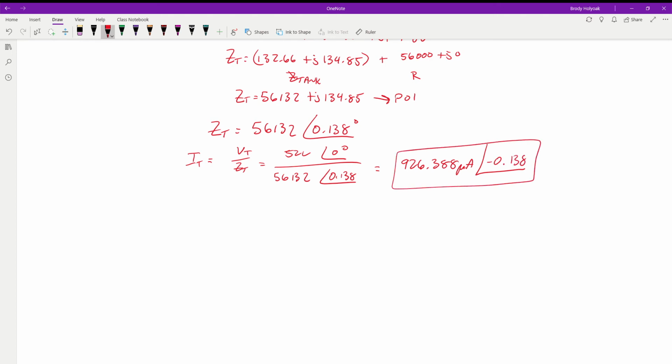Now, the reason I was hesitating is I was looking at this myself. I have to make sure I have my brain wrapped around it, and sometimes I jump ahead on the steps in my notes. Just to explain my thought process, I was thinking we're solving at our critical frequencies, F1, F2, so these should be closer to 45. But we're not. We've gone way outside of our bandwidth, and so that's why we're getting these weird angles. But these are what we should see in the circuits: the farther we get out, the smaller the angles get. Everything pretty much comes down to zeros at the end. And at our 3 dB points at F1, F2, that's when we're going to see these 45s.